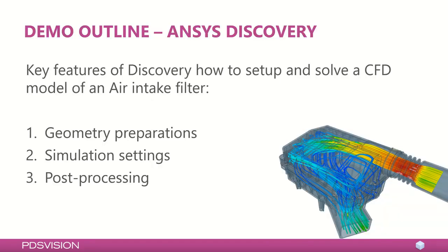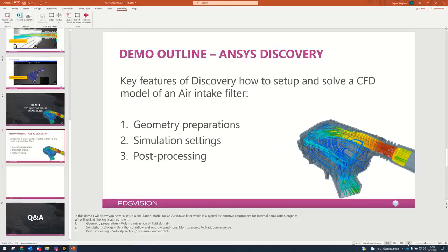So in this demo, I will show you how to set up this simulation model, showing you the geometry preparation and the fluid volume extraction. We will do the simulation settings, defining the inflow and outflow conditions, and tracking convergence by adding monitor points. And then at last we will do some post-processing of velocity vectors and pressure contour plots, etc. So let's get started.